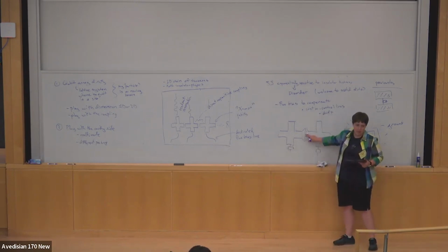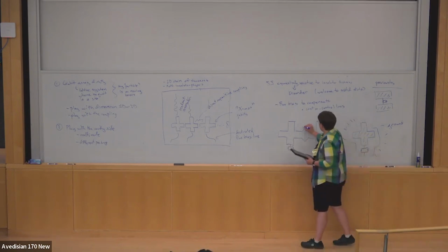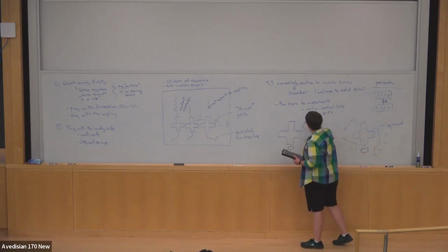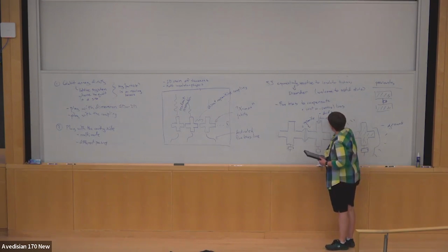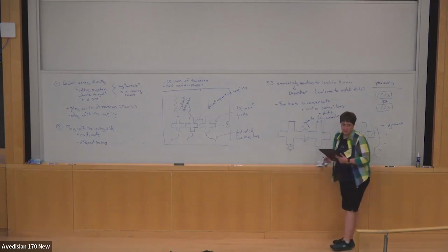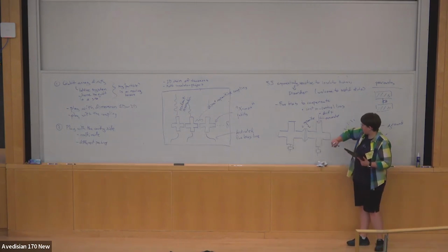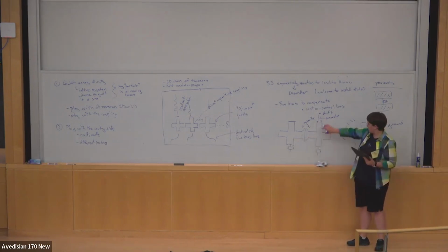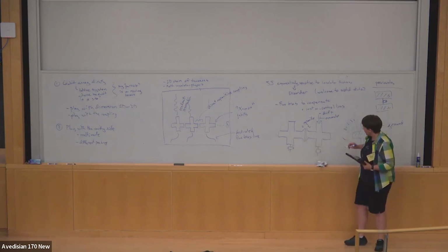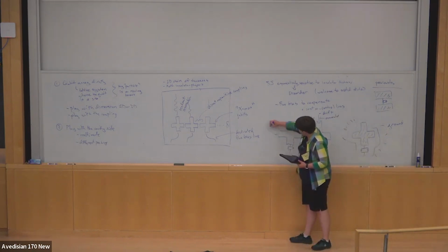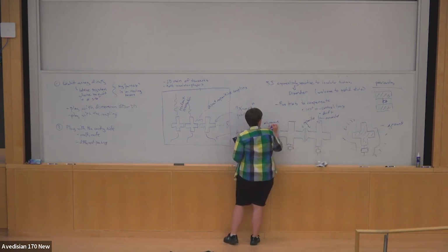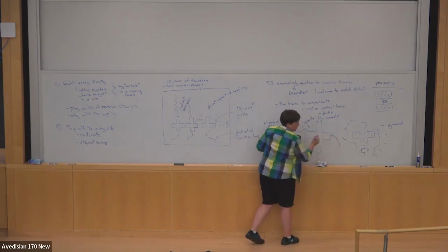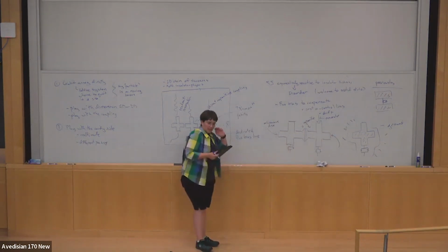And so by changing the shape over here, I control the capacitive coupling. And then the shape over here is going to control the resonator coupling. So if I want this capacitance to be small and that capacitance to be big, I just change what goes on at this end versus that end. And there's still an extra arm for microwave drive to come in like so. And so that's kind of the nice thing about the XMON.